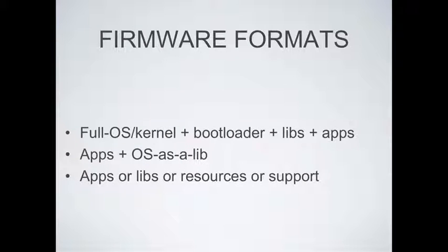What type of formats is your firmware going to be in? It depends on what type of system you're looking at and how it's been implemented, how people are pushing firmware updates, or how they're going to be supporting their product after it's been sent to the end user. You could have a full-blown system with a full OS and kernel, a bootloader, and possibly some support libs and the applications. But if it comes in this full-blown version, the applications are usually running in user mode.